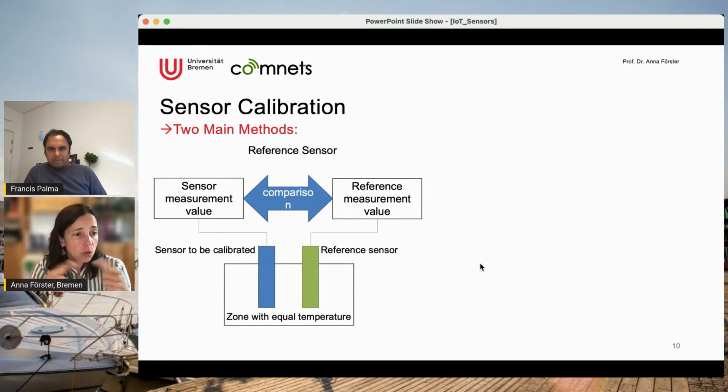And then, of course, you can measure the difference. You can see, okay, at the temperature 25 degrees, I measure this electric signal. When I change it to 10 degrees, then I measure that electric signal. Okay, something else. And now this linearity comes back into the whole story. Because if it's a linear function, you only need two measurements. You can measure at 10 degrees, you can measure at 25 degrees, and you draw a line in between. Unfortunately, not always are things so easy, so you need to make more measurements and then fit a more complex function over that.